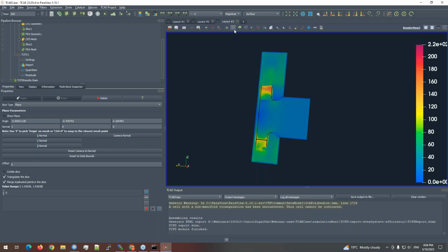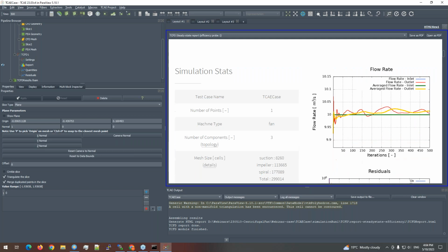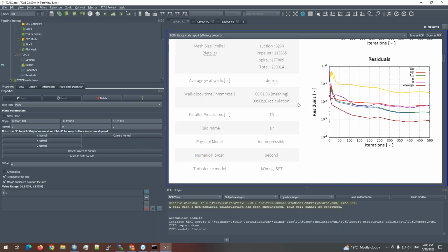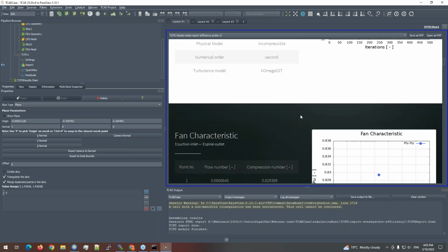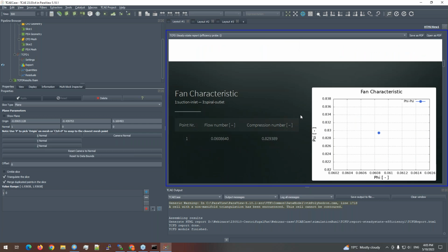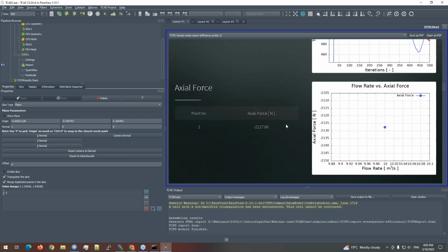All right, and maybe the final part is the report. So at the end you will see a report like this, which summarizes the CFD simulation itself, and a similar report you will also get for the acoustics module, for the FEA module, and the workflow still remains the same. So for the FEA you will just input the STL of the solid part, create a mesh, preset the FEA parameters, which are much simpler than for the CFD, and get all the results you want.